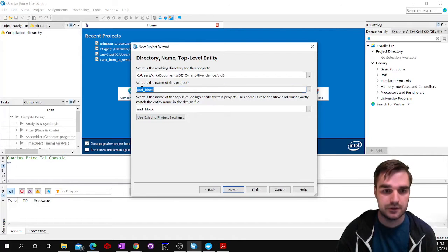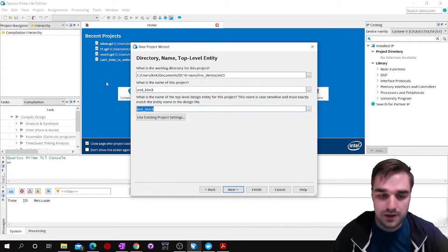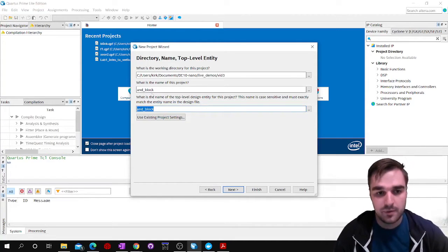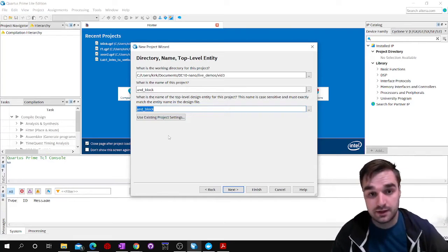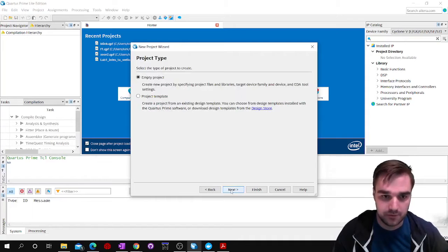You're not really going to see where that comes in this video because we're just going to have one design file, but all the names have to match. As you start doing more complicated Verilog designs, you might have second and third Verilog files that you're bringing into the main top level entity, because this is a hierarchy, like a parent-child relationship. Anyways, I'm going to call mine _block, and I'm going to stay consistent with that naming throughout this project.